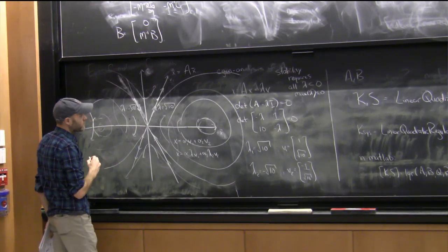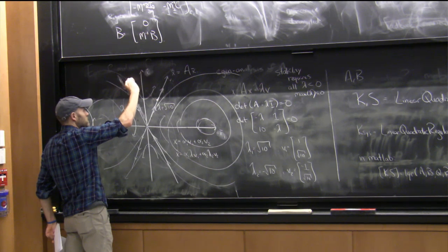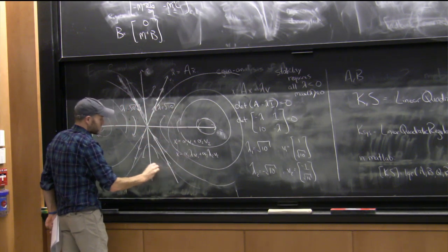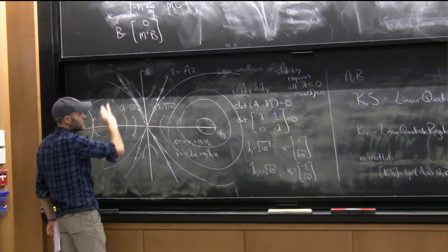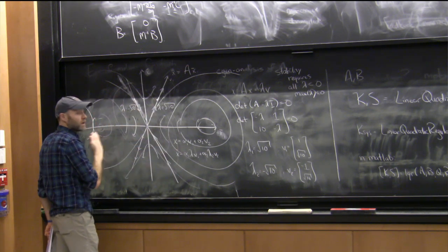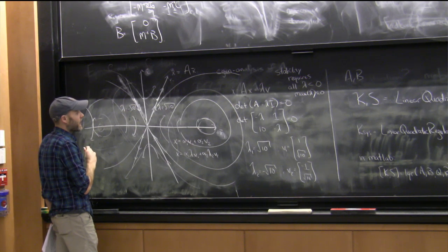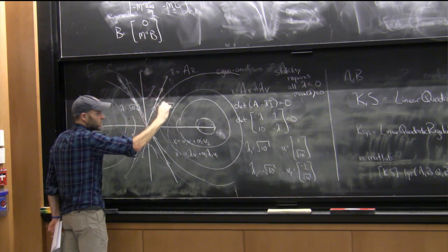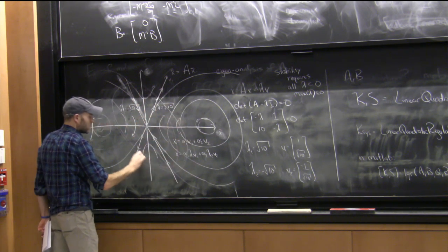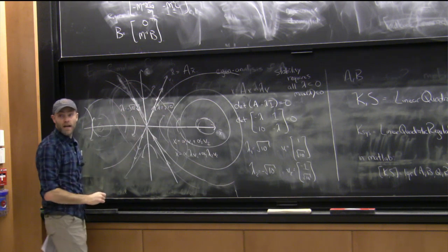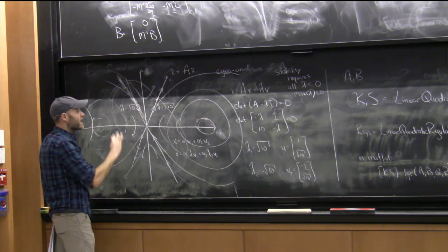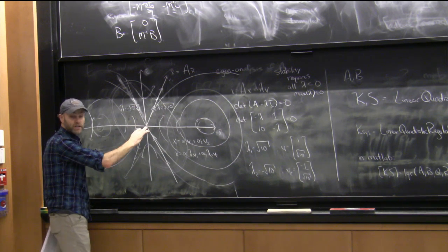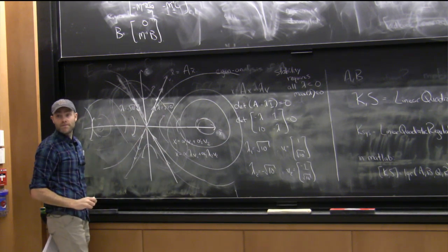So in these plots that I've been making, there's a question that I'm just going to set up now and we'll talk about next time, which is, can I identify a subset of this state space? For instance, maybe it's a sublevel set of J. Like a contract that I might like to have is that if my cost to go is less than some number, which means I'm inside one of these rings of the contour plot, then I'm guaranteed that the nonlinear system using the linear controller is stable.